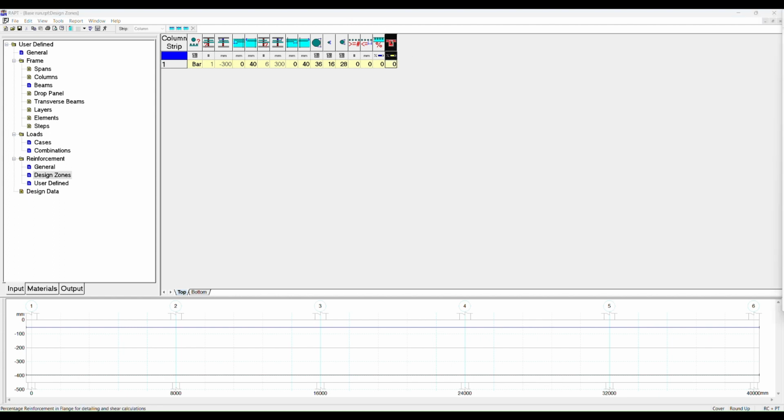That has an impact on your shear calculations because the number of bars inside the ties, in other words, not including the bars in the flange, are what are used as your steel reinforcement for shear calculations.